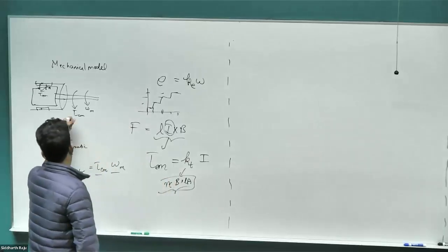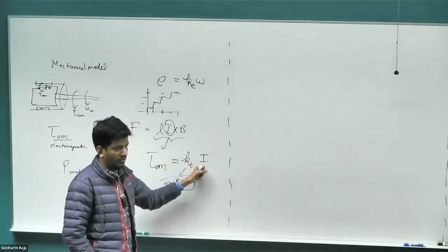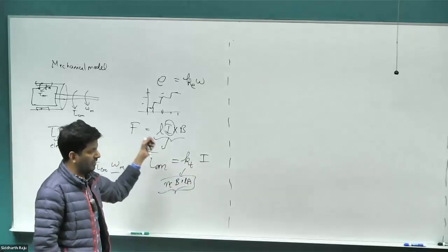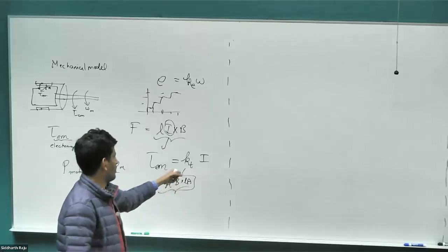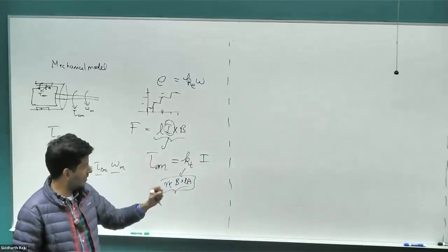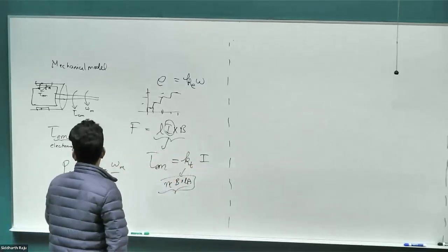So the way I change the torque is basically flipping the direction of the current, right? That in turn would mean you would have to use some kind of power electronic converter, which is basically changing the voltage so that the current can then reverse. But the idea is you need to flip the current direction. Okay, so